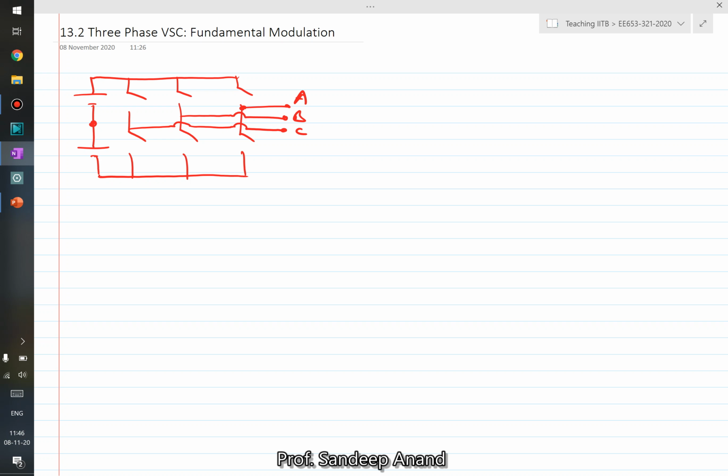And if you see on the DC link, although if it's a three-wire system, you don't necessarily need this middle point. Let me call it O. So this could not necessarily be an actual middle point because nothing is connected here. It could be a fictitious point which we are just imagining, just something we are doing for the derivation. But if it's a four-wire system, then you physically need the point O so that you can generate the fourth wire, which is going to be the neutral wire. So let's start with analyzing this circuit.